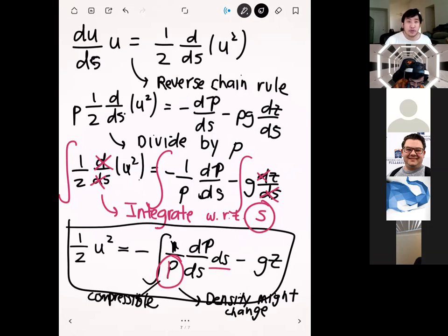But there's another force here that can drive flow, which is gravity, and we'll get to this in a bit. So if you have gravity driving your flow downwards, like for a waterfall, you can have the same pressure upstream of the flow and downstream, because there's no need for a pressure difference to drive that flow, because gravity is basically doing all the work. And so the places where you don't see a pressure gradient, oftentimes you have gravity driving the flow. That's usually the most common place.